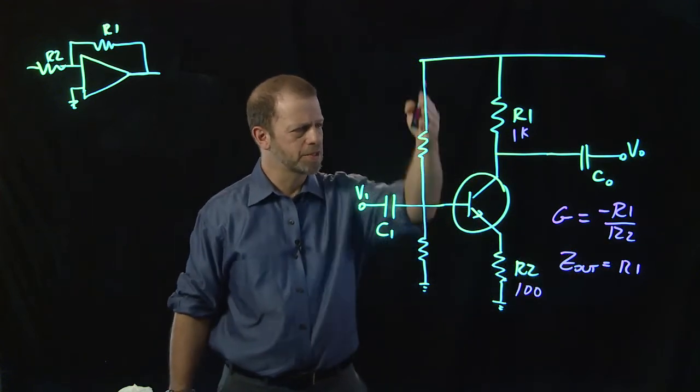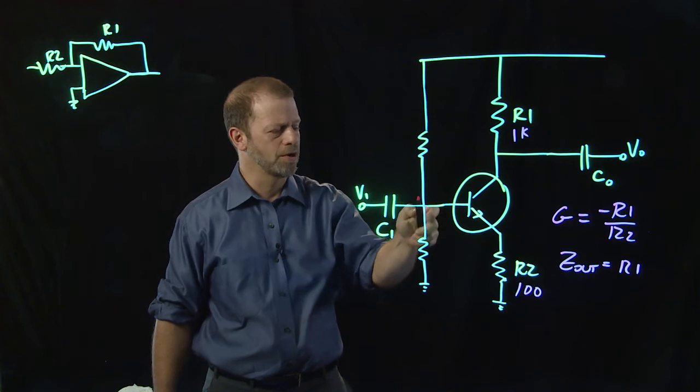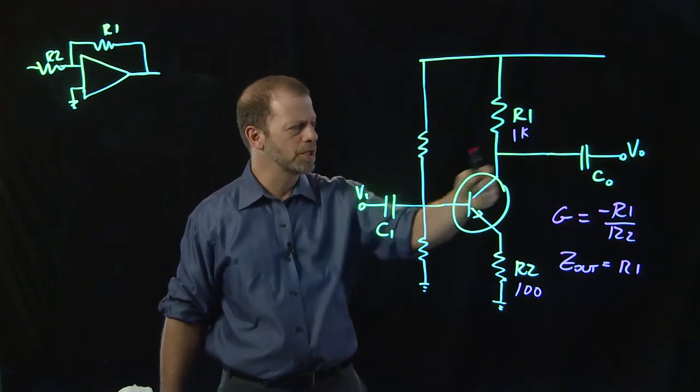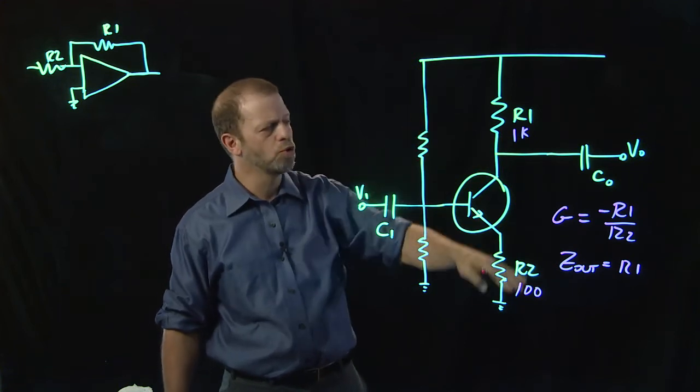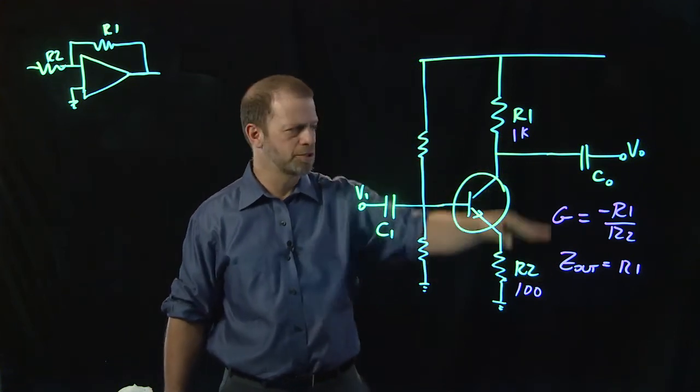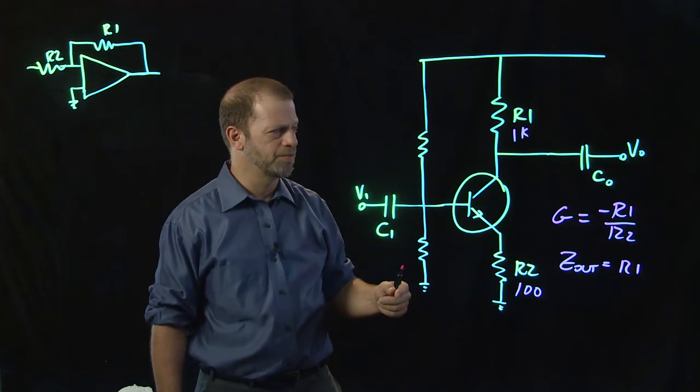And we've biased this by creating this voltage divider here to bring the base to just such a voltage that the output voltage is 2.5, and that gives it plenty of room to roam to lower voltages and to higher voltages as this behaves as an amplifier.